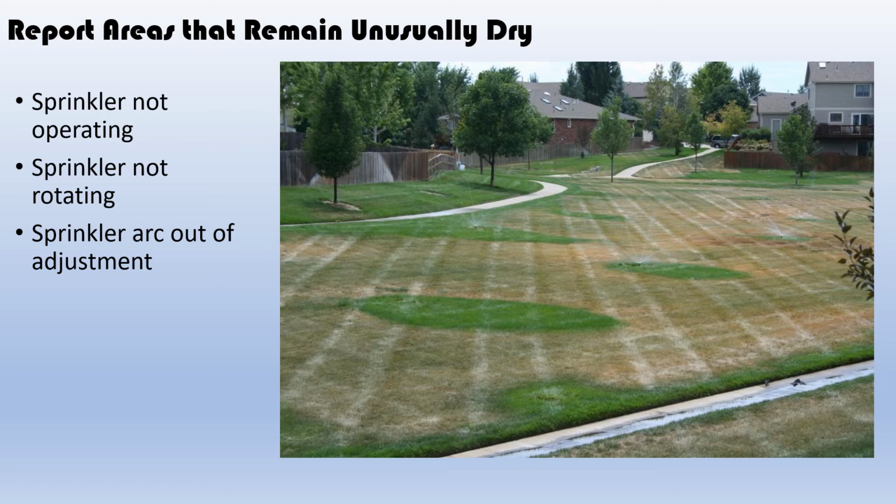If you regularly find a dry spot that doesn't make sense, in that the area is not sloped or weather patterns don't indicate the need for an increased water requirement, then the issue may be caused by a sprinkler problem. Typically, uniform stress has a mechanical cause, and this picture is an extreme example of that. However, it illustrates how you see these fairly uniform patches of green grass, then you can clearly identify that the reason the rest of this stand is struggling is it's not being covered by the sprinklers as intended.